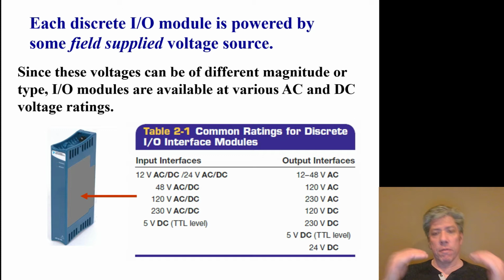So there's all these different voltage levels that are very useful depending on what type of device you really want to use. You might wonder, why don't they make all these devices just operate off of one control voltage? Well, it's for flexibility. There's many reasons not to. Having to do with distances, AC and DC act differently over distances, and so there's many reasons why you would want an input-output module to be able to support a particular output voltage or input voltage specification.